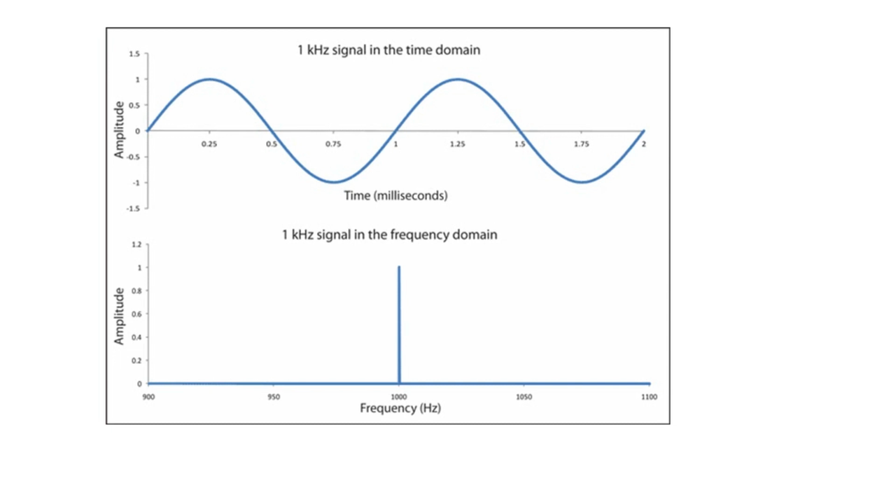Now when the same kind of signal information, that is the 1 kilohertz signal, is represented by using the frequency domain, here in this graphical plot, on the horizontal axis instead of the time, we have the markings of frequency in terms of hertz, and again the amplitude level on the vertical axis. Now you see the visualization compared for both the plots. The signal is the same, that is 1 kilohertz signal here, but as the representations are in different domains, the visualization or the nature of the graph seems to be different here.